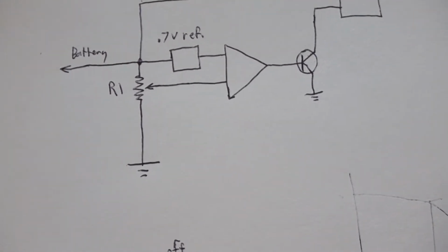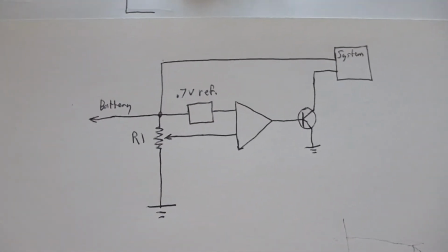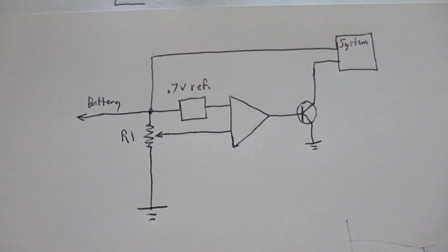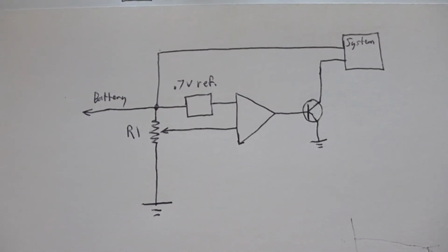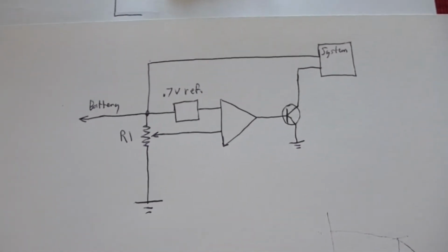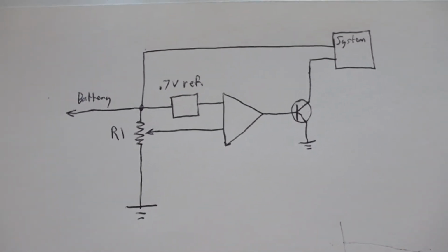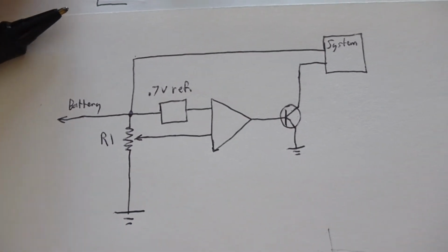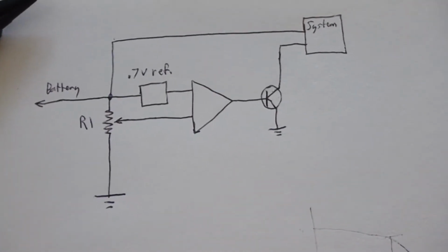You can say, oh, well, I'll have another battery. If you have another battery, okay, now that one needs to be charged and it needs its own regulation circuitry. So that problem comes up a lot. So the ultimate solution to this, you might be wondering what that is if we're not using our comparator circuit. The ultimate solution is to use a voltage regulator.